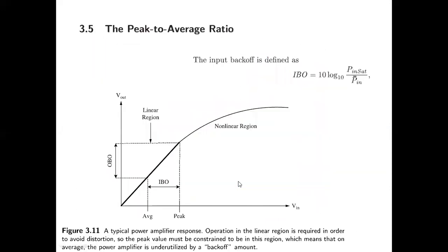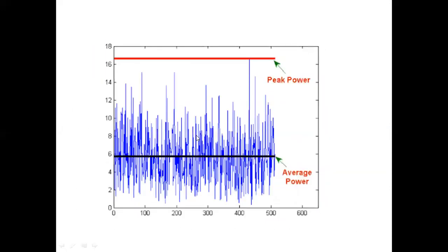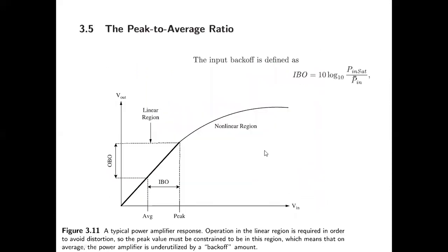And what's going to happen is, if your peak power is very high compared to your average power, then you will have to bias your power amplifier in a larger region. If I want to drag this line further higher here, you can see I will need much more biasing. You remember when you are doing your RC coupled amplifier, or your common source amplifier, common drain amplifier in your electronics lab, there are two things.